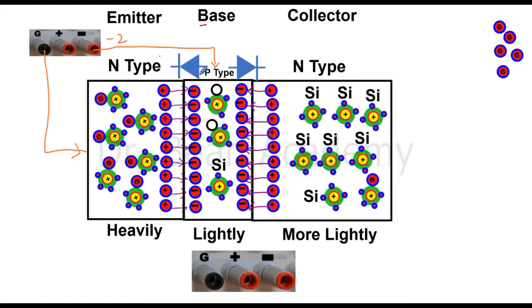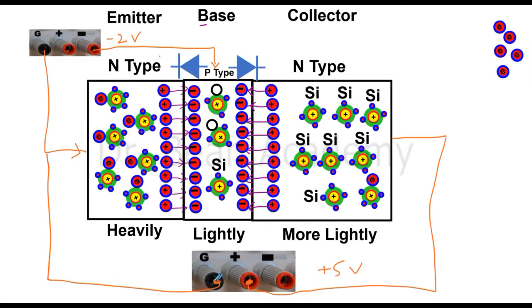So you see now I am connecting the base with a certain potential. Next I connect the collector with the positive terminal of this power supply here, and I set this potential at +5 volts. Of course, all the values are in volts. And this ground is of course 0. Then I connect the emitter with the ground. So you can say that this ground and this ground are actually the same ground.